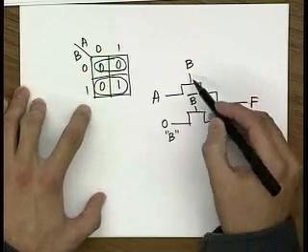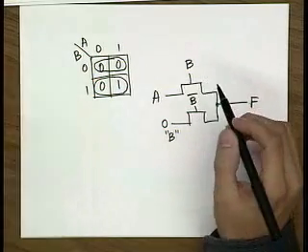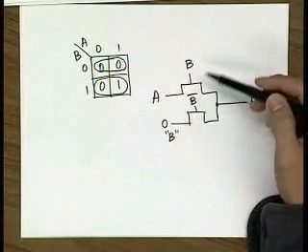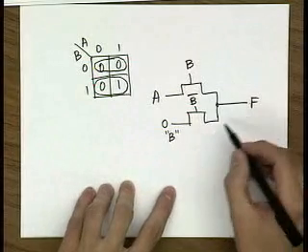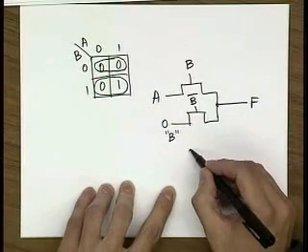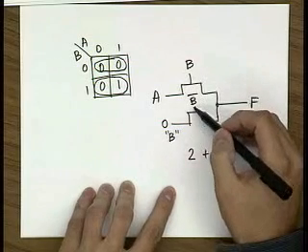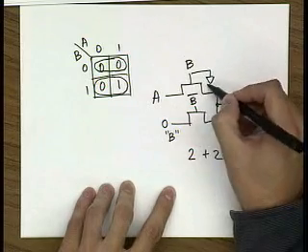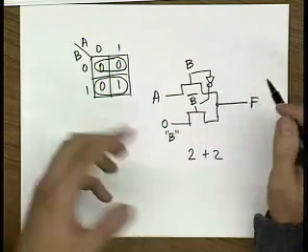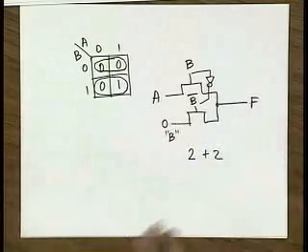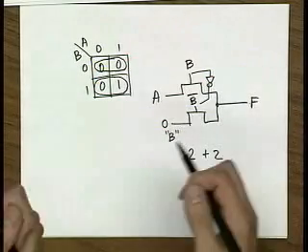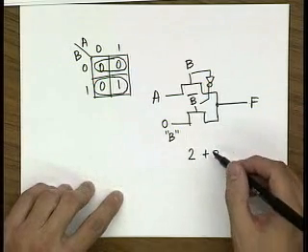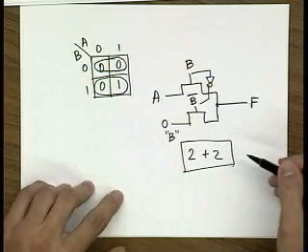And now the question, as you just pointed out, is the issue of generating these complementary signals. For the implementation of the AND function, you need 2 plus 2 transistors, because you also need to provide this B bar, if you assume that you can use an inverter over here. Or we will see later how you can do this in fully complementary form, such that you have inputs switching at the same time, true and complementary. So this is 4 transistors.